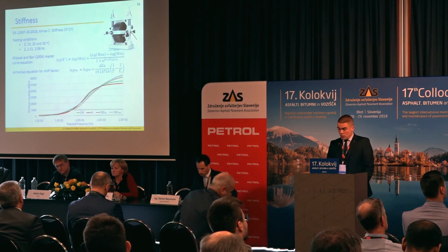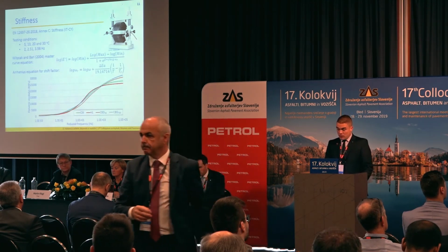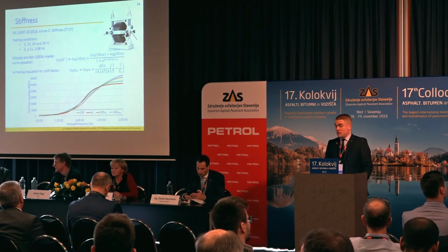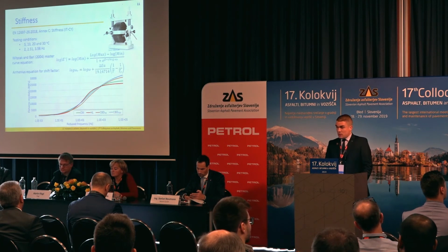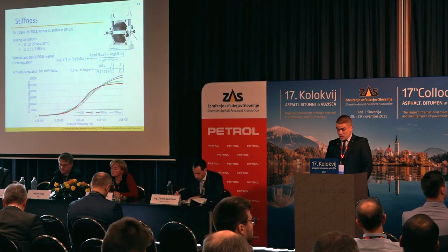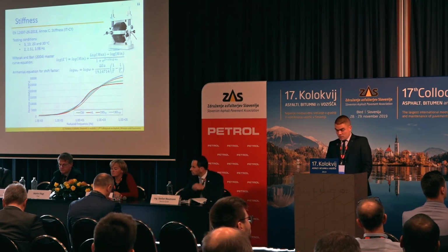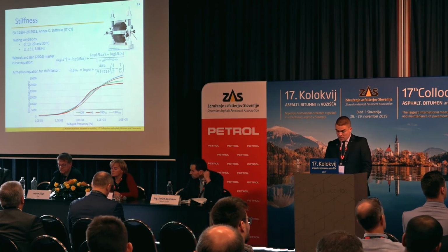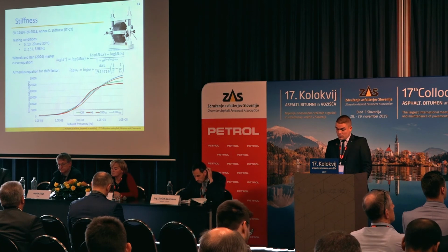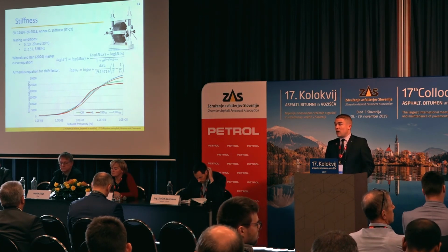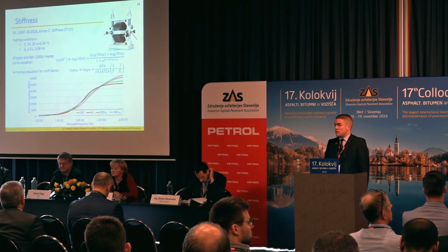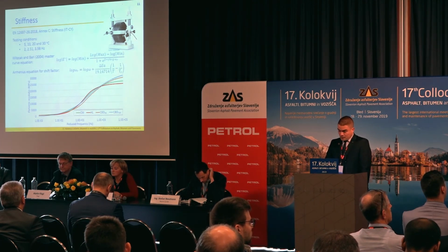Testing results show that in the domain of low temperatures, the mixture with hydrated lime had the lowest stiffness, while mixtures with cement bypass dust had much higher stiffness. In the domain of high temperatures, it cannot be clearly seen, but mixtures with cement bypass dust had slightly higher stiffnesses, and that actually was approved before in the test with rutting resistance.